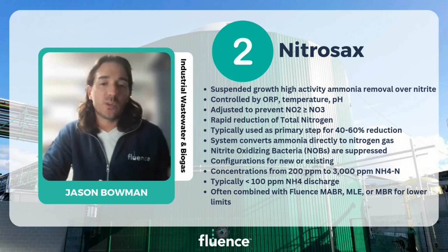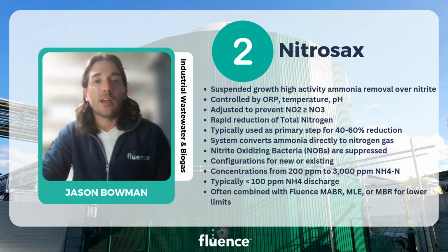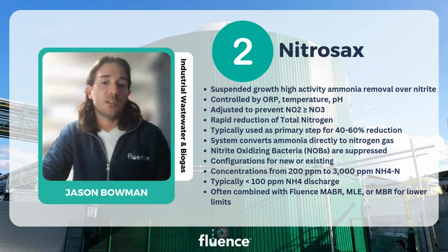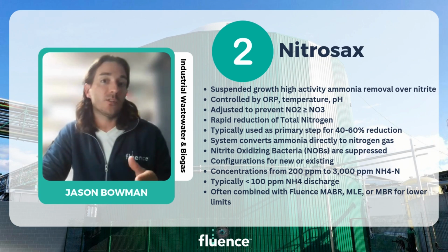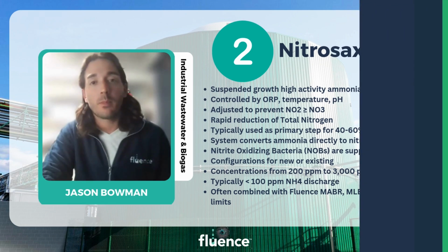So for this reason, we often add secondary biological treatment or even filtration after this type of process. So this could be an MABR, as we've already discussed. This may be an MBR. This may be a more conventional process, etc. So we'll talk about these other technologies in the upcoming slides.